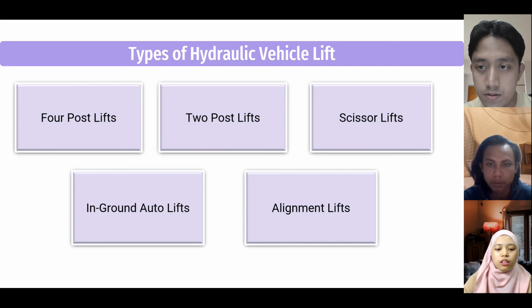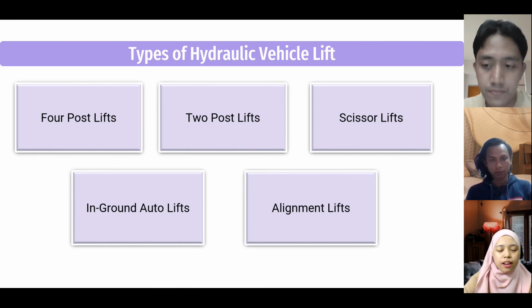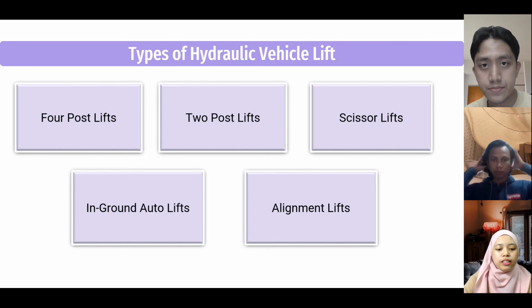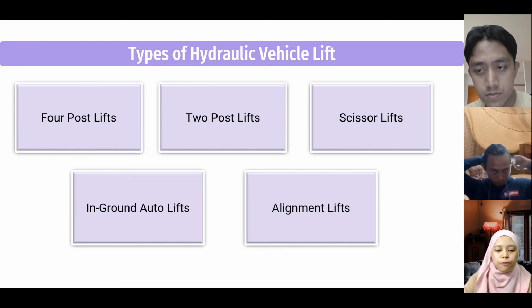The 4-post lift contains 4 posts at each corner and a ramp-like elevating platform connecting them. This helps the vehicle get on. 4-post lifts with different lifting capacities and base area dimensions are available in the market. Users can select the required lift by considering the specifications. The powerful locking system used will help to position the vehicle at the required height and prevent accidents.